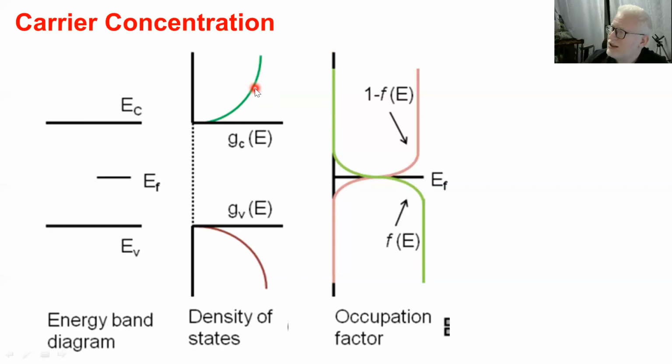But in the other case, there may be a probability, however there are no seats, which is the case for the Fermi level. And then there are no electrons or no holes. So now we should agree that the Fermi level mathematically is the level at which the probability to find an electron equals the probability to find a hole, equals 50%. Very simple. And it's located in the forbidden gap.